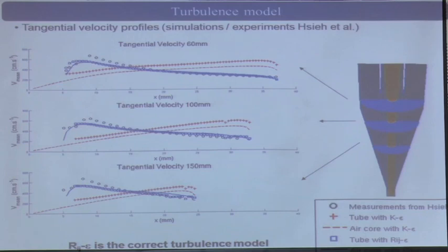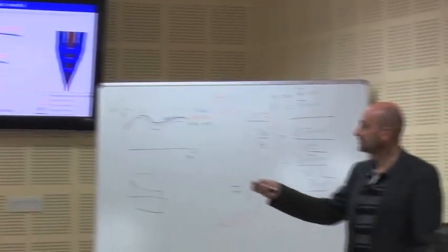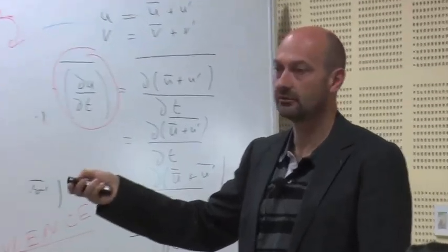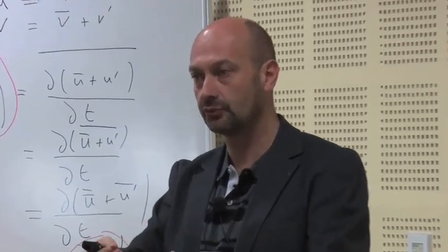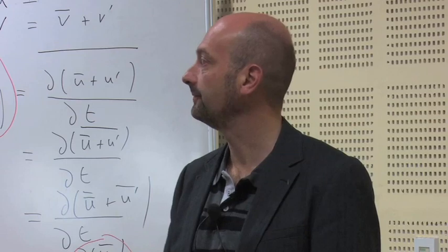Okay, so of course, I was expecting that the turbulence is not isotropic, but I decided to use K epsilon as a first guess. And then when you refine, of course, when you go from K epsilon to RSM, the time of the simulation is multiplied by 10. Okay, so you have a better answer, but you lose time. Okay, but still we had the first guess with that flow, which is not correct, but you can use that as the first estimate to run a better simulation.